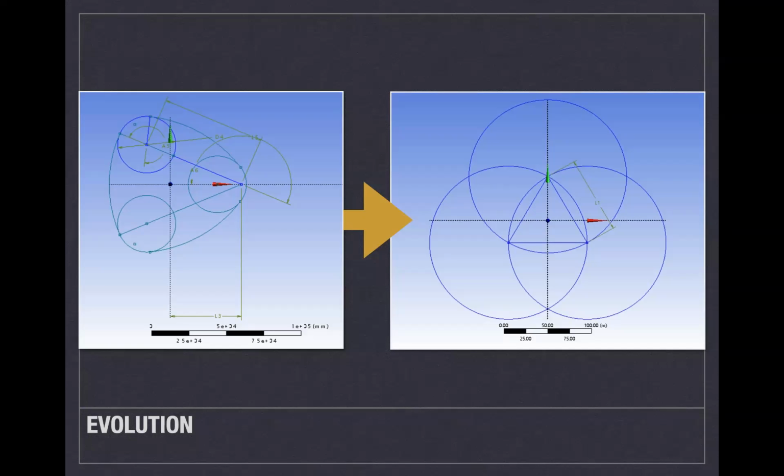This is a Reuleaux triangle, and it has an arc length on the base of approximately 94.25 meters, and we contracted it to approximately 47.12 meters on the top of the tower, and that worked really well. So it is a successful simplification.